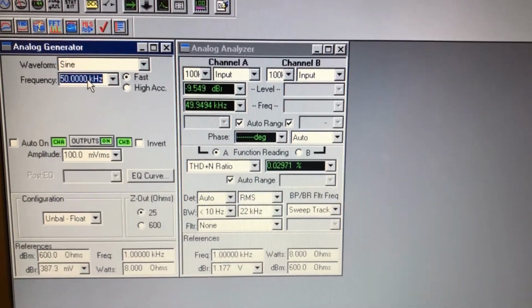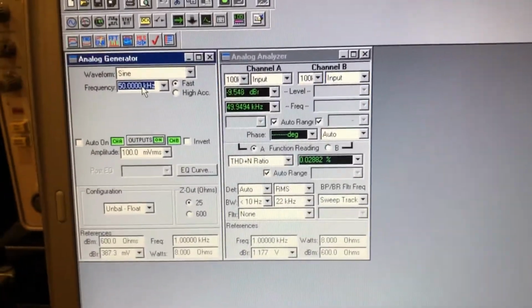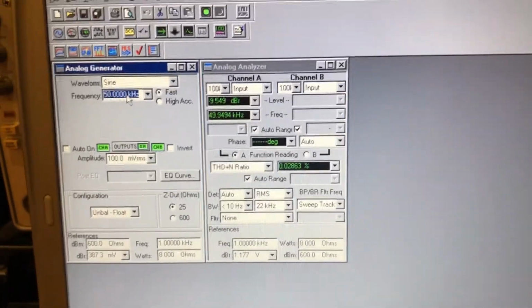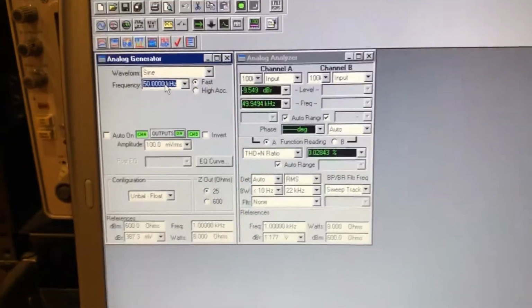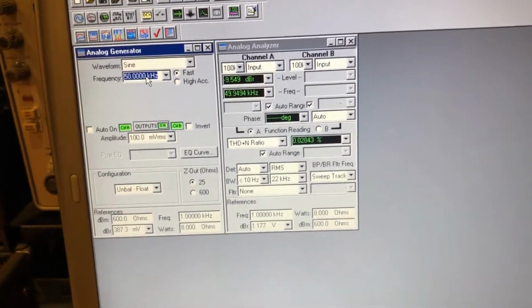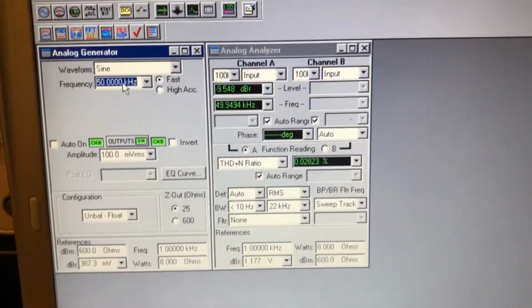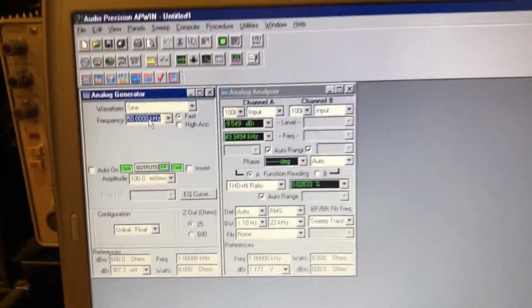It's pretty bad. You can see the AP says 9.55 dB down at 50 kilohertz. Of course, this actually isn't real, and again, this is where you need to be careful if you're doing this sort of work. You have to think through what loads your equipment represents to the circuit you're trying to measure. So 50 kilohertz is not really 9.55 dBr down.